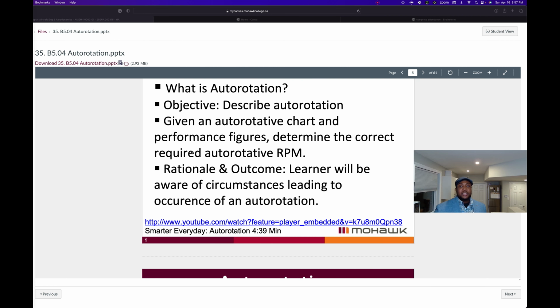During autorotation, this section is our most crucial section, as it supplies the thrust that is needed to accelerate the rotation of the blades. This driving region is also known as the autorotative region. Keep that in mind. So we have the driven region, and the driving region, which is also known as the autorotative region, which is the useful region that actually helps us produce lift.